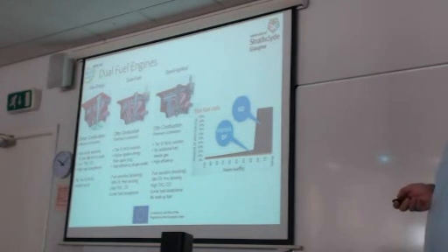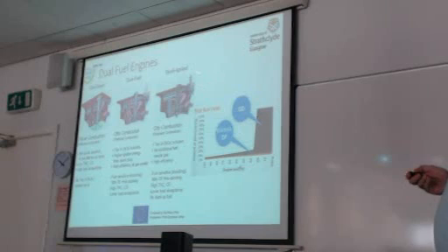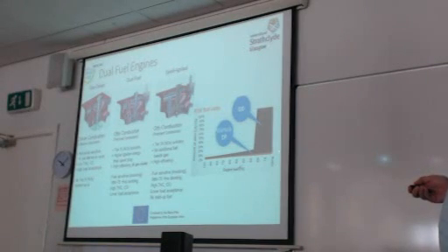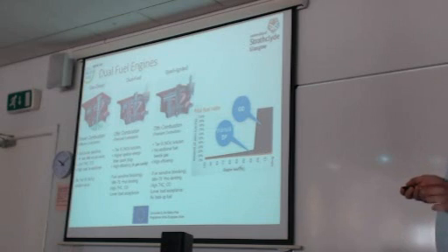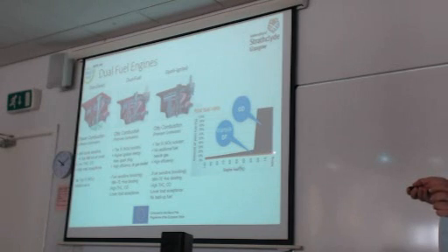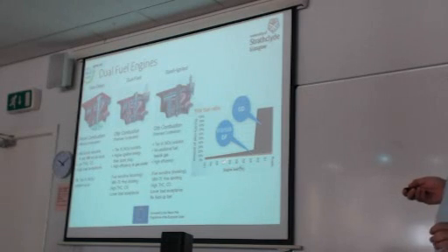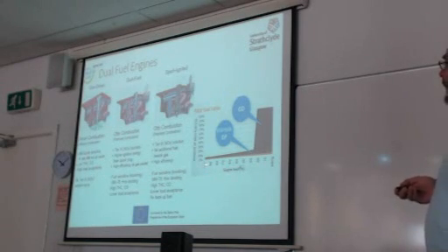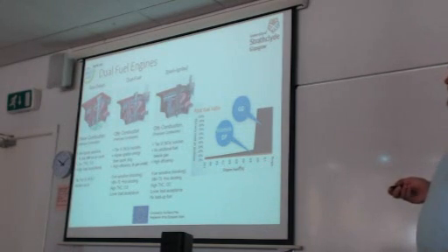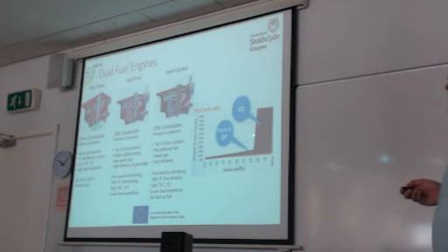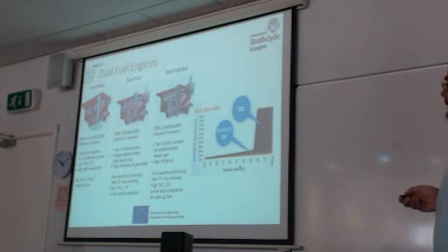So let's discuss a little bit the advantages or disadvantages of each one of the mentioned types. As I said, we have the gas diesel engine, the dual fuel engine and the spark ignited engine. Just to mention that in the case of dual fuel engine, the pilot fuel percentage is only up to, let's say, 3%. As you can see here from this orange strip, in dual fuel engines, the pilot fuel, the liquid fuel, is from 1 to 3% of the total fuel amount.